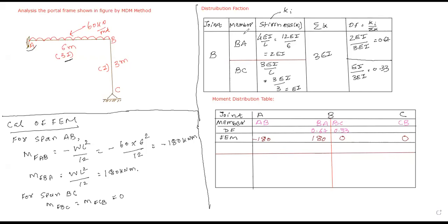Think, we have already calculated such an example. We have only 15 minutes. We need to complete this table today. Fast. Now, what is the nature of point C? Write down in the chat box. Now, a hinge support cannot resist any moment. What is the moment at CB?